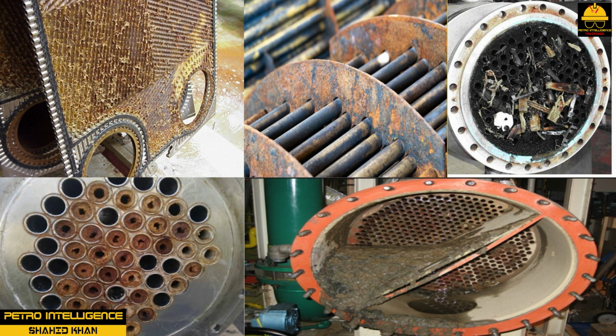Other problems associated with heat exchangers include internal or external tube leaks, gasket leaks, tube sheet leakage, damaged or crushed tubes, air-cooled fins that are crushed or fouled, decreased flows due to poor pump performance, sheared tubes, or air trapped in the shell. A heat exchanger's effectiveness is typically linked to three things: first, flow rate of each process stream; second, temperature differences between the two opposing streams; and third, the cross-sectional area of the heat exchanger.